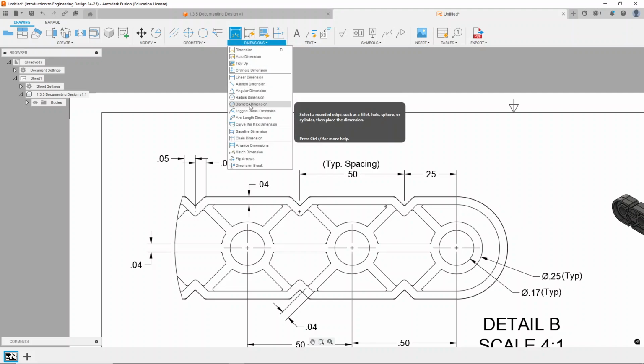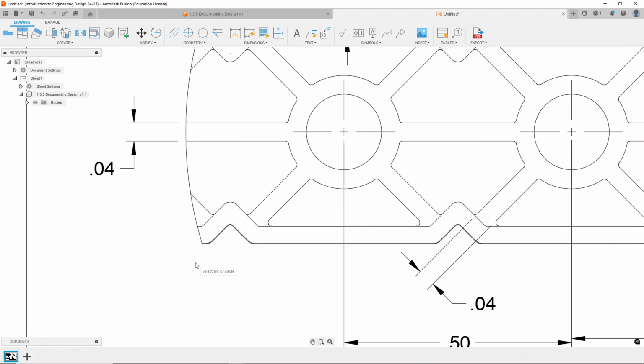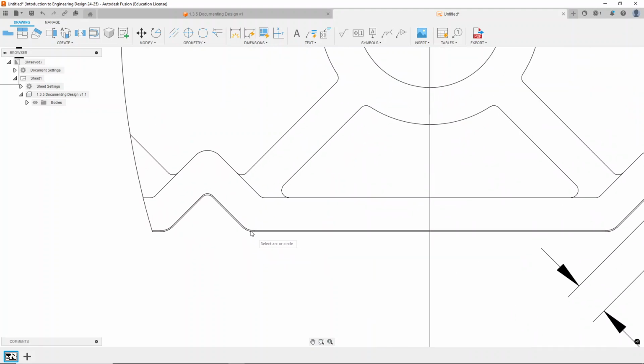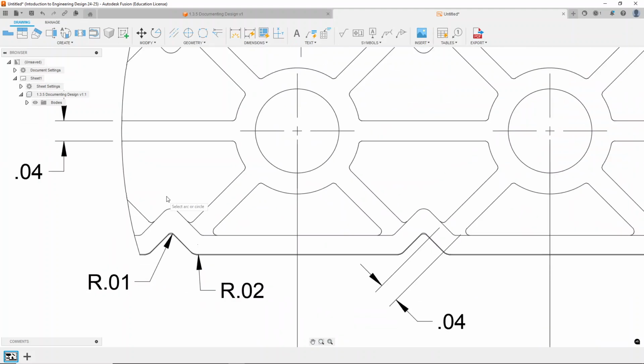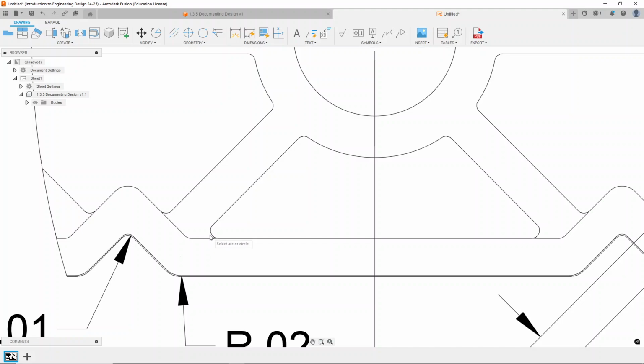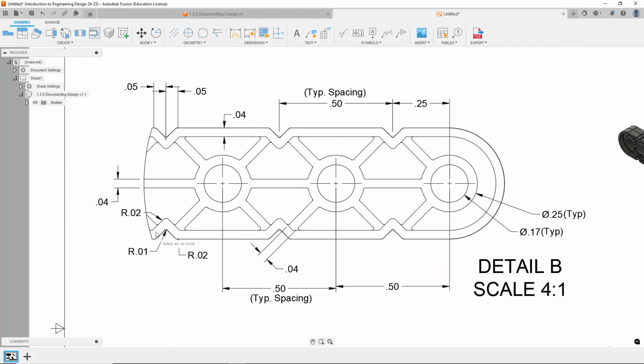So for our dimension tool, go to our radius dimension for that fillet that was applied to all of these. So we're going to get this curve. We'll have it going to the right, the inner curve. And then we'll go with these inner curves as well, if it'll give me that geometry. No, it will not. Well, that's unfortunate. So we'll just grab this curve up here then. So now I have the radius of each of those curves as they move around.